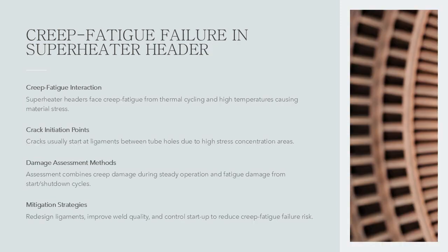This case highlights the importance of proactive assessment to avoid catastrophic failures that could result in costly downtime and safety hazards. Superheater headers and heat recovery boilers often experience severe creep fatigue interaction due to frequent thermal cycling and sustained high-temperature exposure. Cracks typically initiate at ligaments between tube holes, where stress concentration is high.